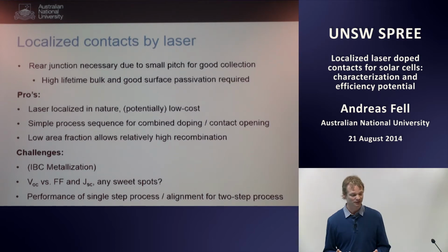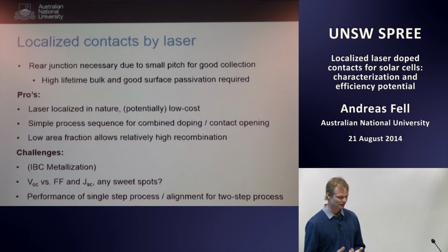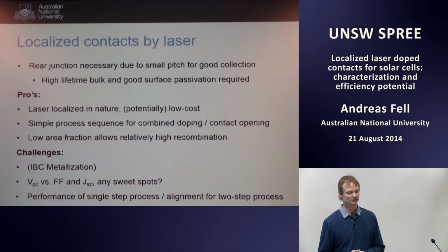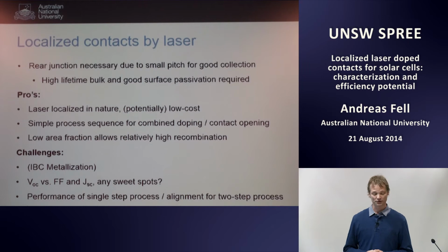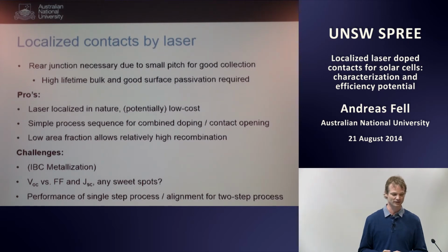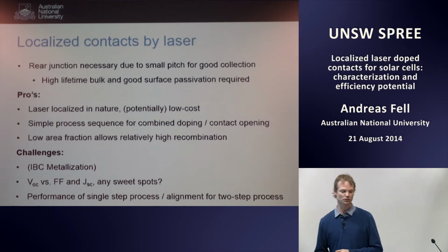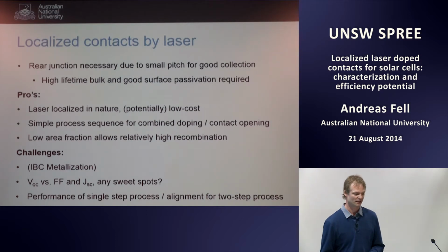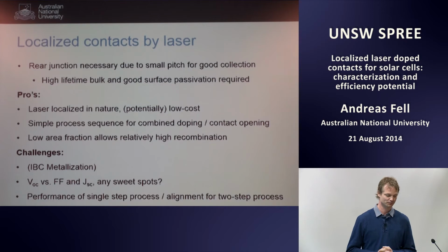Nobody would be interested in that, I think. What we're interested in is a high efficiency cell device, and by high efficiency I mean maybe 23, 24% with a rear junction solar cell concept. Rear junction most likely means an IBC concept. It could still have front contacts, but they might prove to be difficult as well.